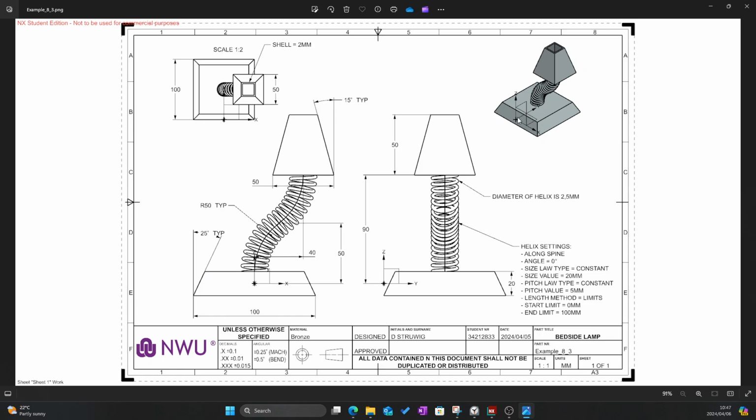You'll see that the sketch origin is situated there, which is in the middle. X to the right, Z upwards, and then Y inwards. It's important to note from this one that the origin is some distance away from the body, and you'll see why this happens, but it's important to get the position of the origin correct.